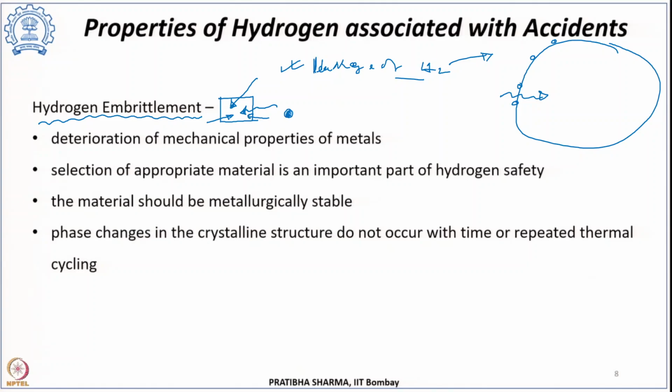Then what will happen is a very critical phenomenon: the material property changes from ductile behavior to brittle behavior. You know that brittle behavior has sudden failure. Okay, I already discussed this in earlier classes also. So hydrogen embrittlement should be prohibited, or should be taken care of.